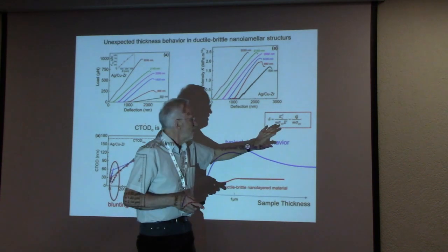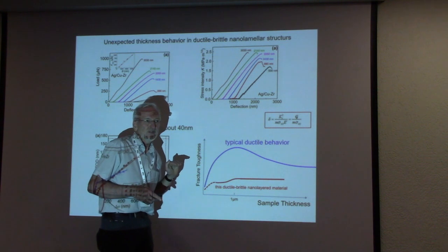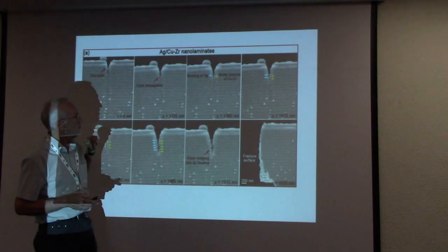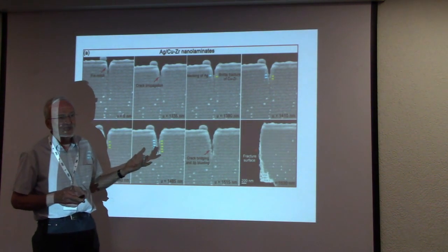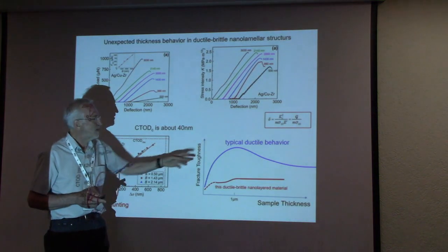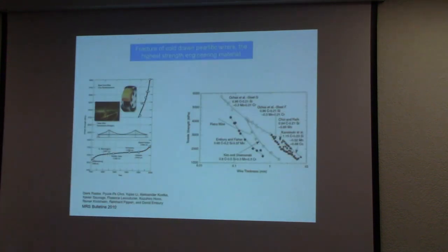And therefore, you can clearly understand why we have this change, because the crack-tip opening displacement in our micro-lamellar or nanolamellar structure is not changed by the stress state, which is in most ductile materials the case. And therefore, we have this different behavior.